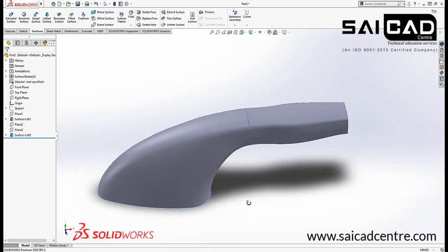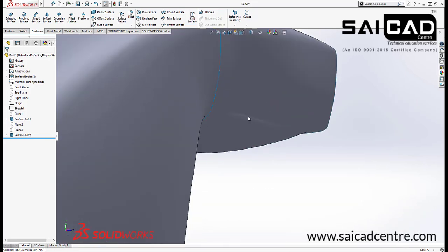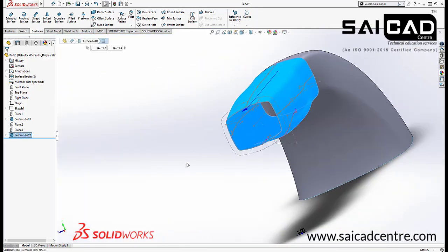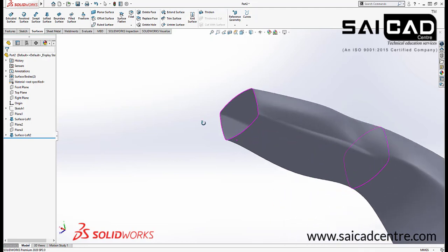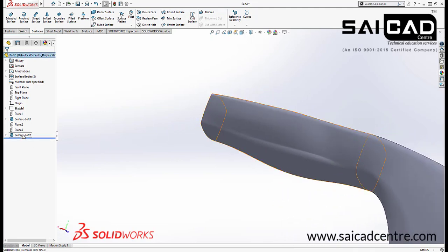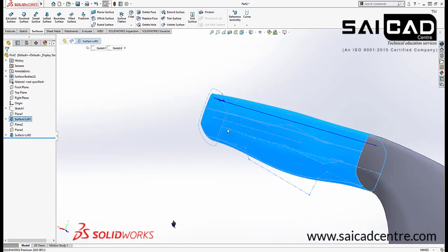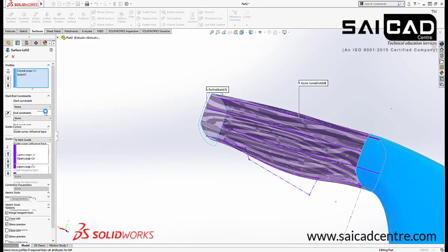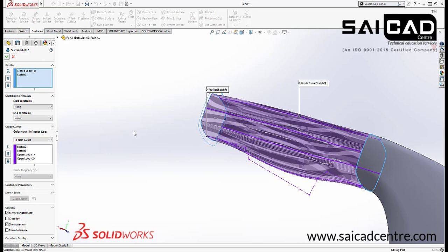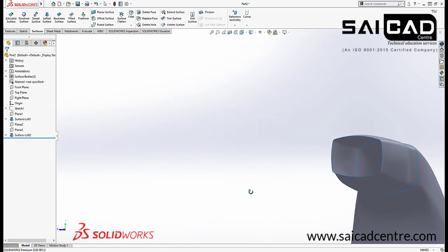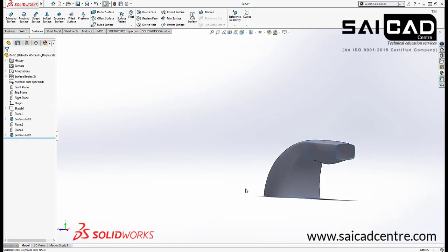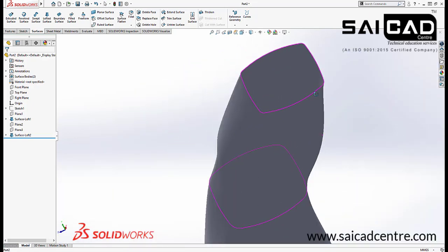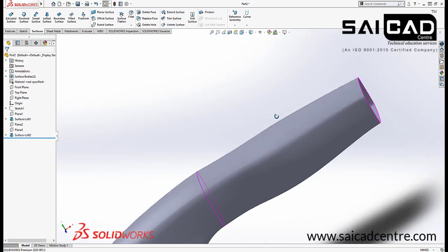So this is the shape. Okay, again some errors here. If I see here, we got some errors in mid. So if I go back, first I will just check by removing that tangency. I will just go to the none. Okay, and I will just see here now there is no error. So you can face some errors, so just use the option and see the object properly.